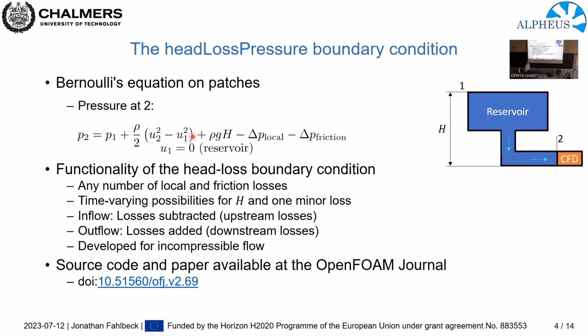The boundary condition furthermore allows for any number of local or friction losses, but it can also have some time varying properties. And important is the inflow losses are subtracted and outflow losses are added. And it's currently developed for an incompressible flow case. And the source code and also paper is available at the OpenFOAM journal, so please have a look at it if you like.